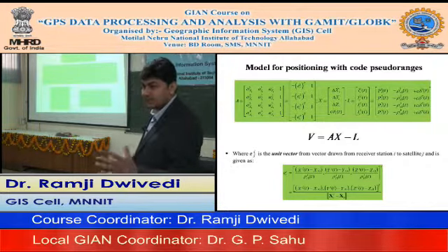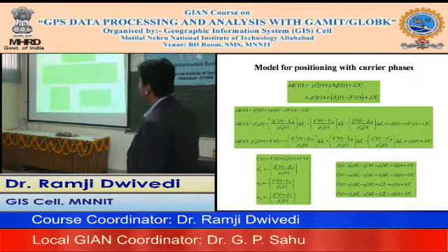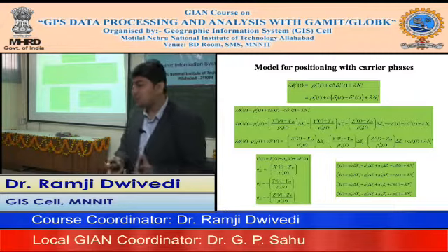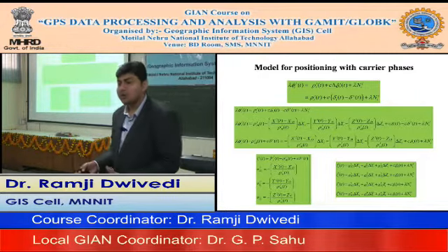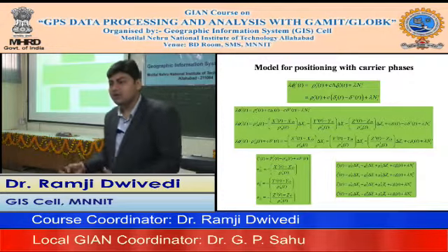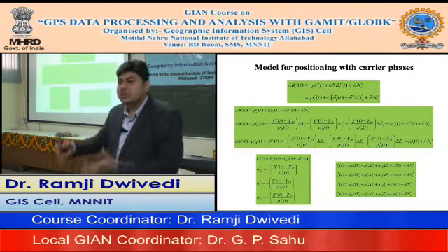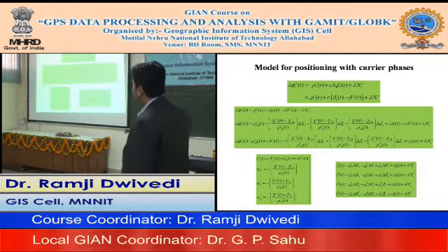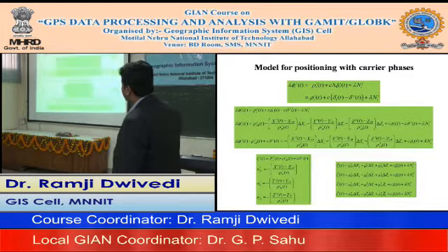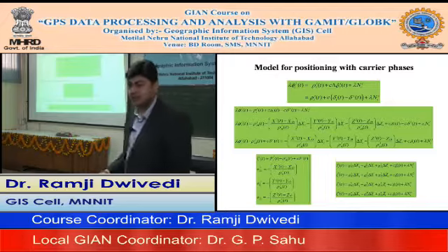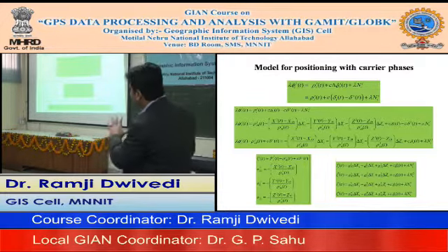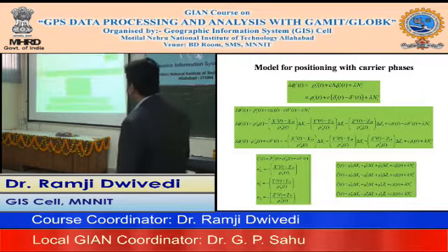Similarly, it is just one step to move to understanding the model for carrier phase also, because we are not only using the codes, we are using the carrier phases also, and eventually the carrier phases are the ones we make so many uses of, in terms of those observations, L1, L2. So we'll see how the equations for carrier phase are written, and please remember that we have skipped those error terms here. Obviously they are there, but for a better understanding of the mathematical model, we have assumed that at this particular time we don't have any of those errors.